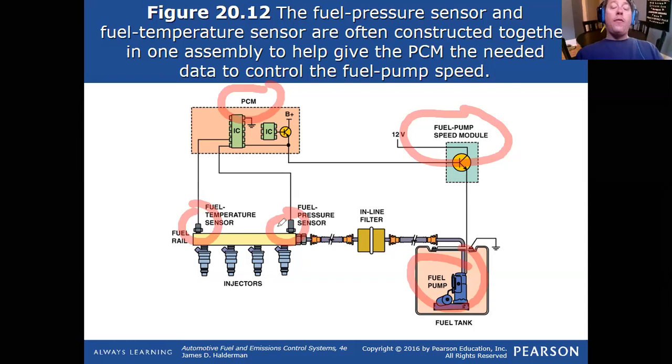It can be that the fuel pump was unable to put out the set pressure because it's just a worn out pump. But it could also be on the feedback side. So the fuel pressure sensor itself, if it's not reporting accurately, you're going to end up with a very confused electronic control system on this engine. And it'll start pointing fingers at different components. And it isn't necessarily the component that it sets a code for.